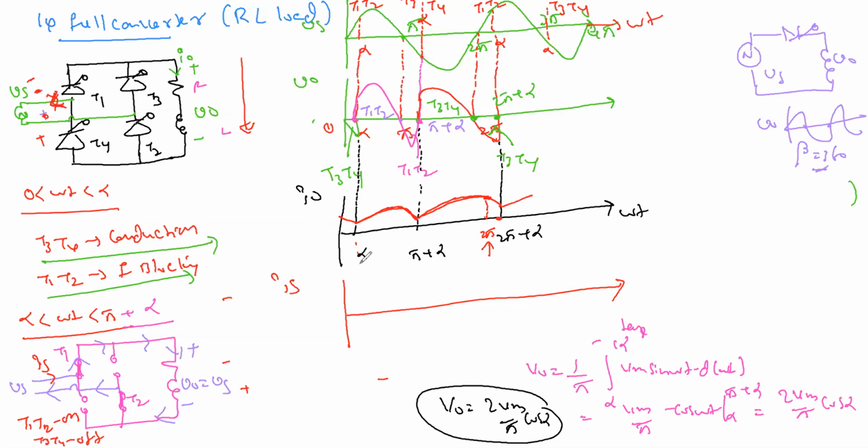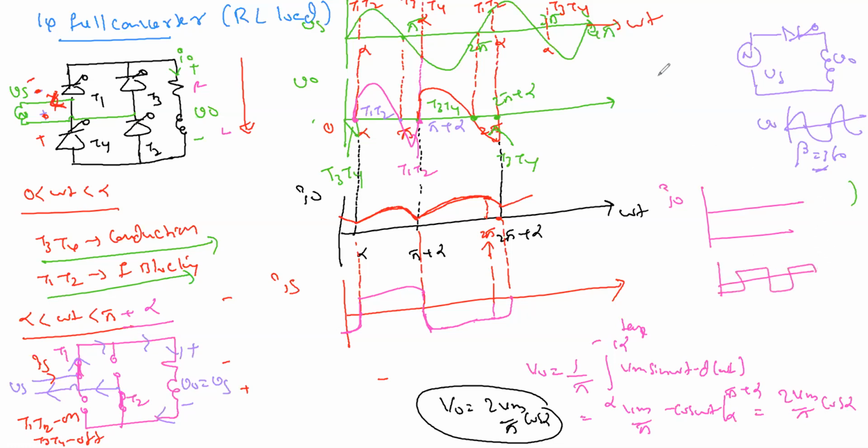Understood? So let me draw that source current. So the same thing, I not equal to IS only, but in the opposite direction, pi plus alpha to 2 pi plus alpha. So this positive direction, pi plus alpha to this one. Yeah, some random. So this is 2 pi, 0. So this is negative in fact. So actually going forward, we draw like a straight line only. We draw I naught as this one, because I'll use high inductance, and IS is something like this way. And this one I'll draw. I'll show that later anyway, going forward.